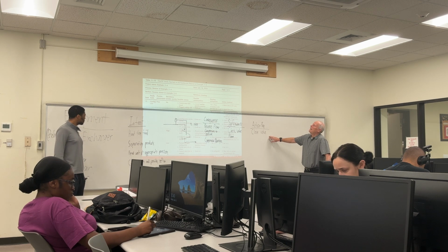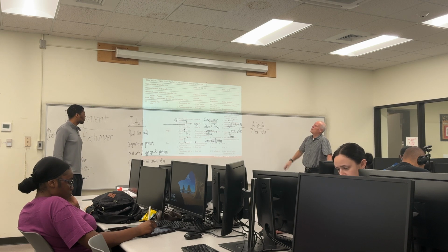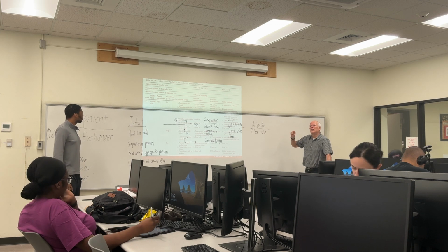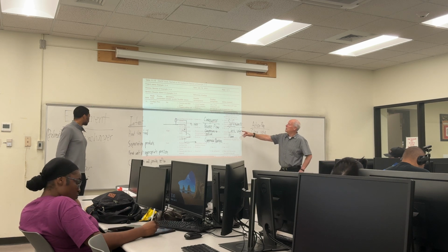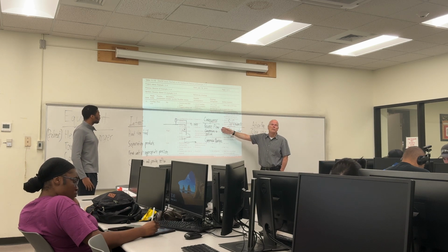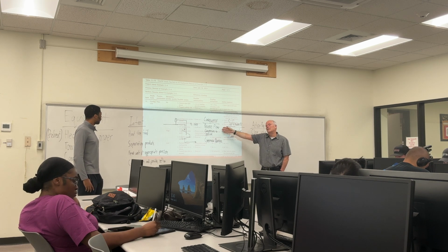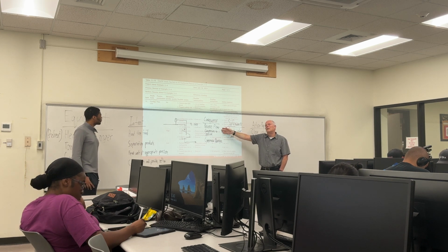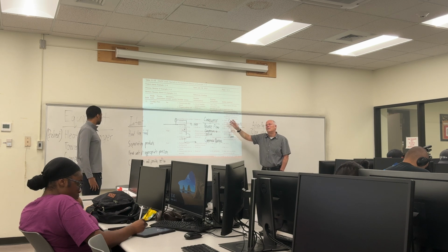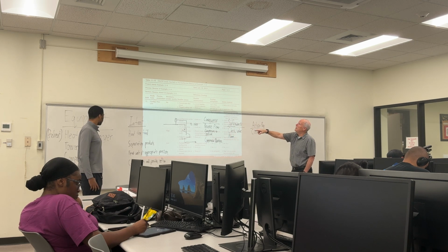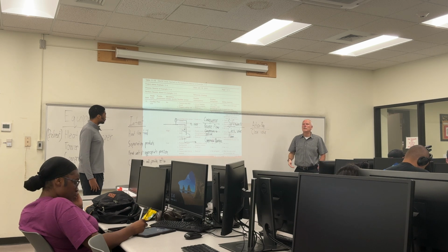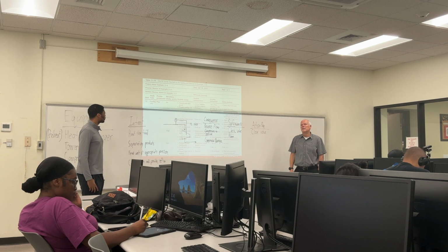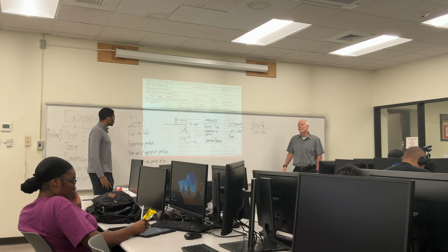Okay? So then the last thing is possible causes. This is where we finally get to our scenarios. These are the scenarios that our HAZOP is designed to come up with. It's important to have the consequences, because you'll need that to figure out the risk associated with it when we do the LOPA on Thursday. But you also need the scenario so that you know the probability. What's the probability that this is going to happen? So you need a scenario for that.